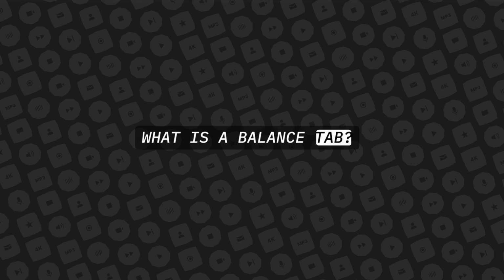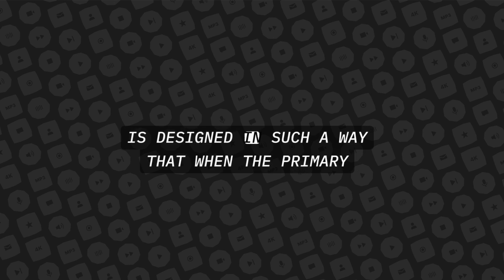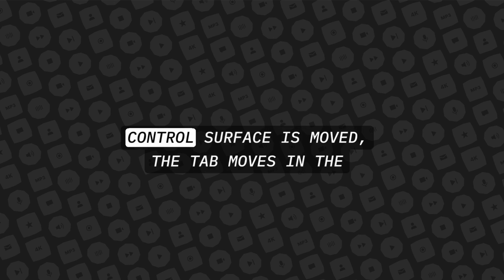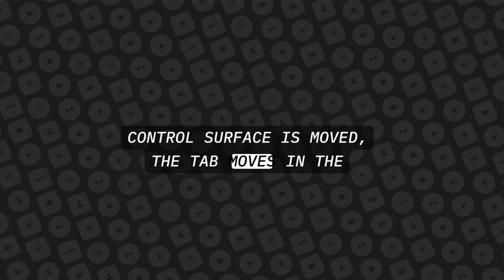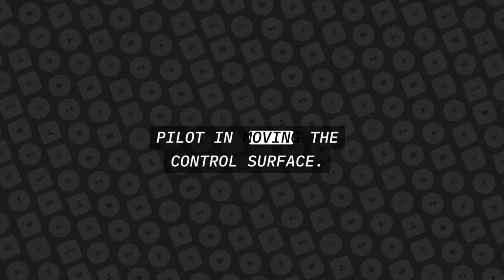What is a balance tab? It is an auxiliary control with fixed linkage that is designed in such a way that when the primary control surface is moved, the tab moves in the opposite direction. Aerodynamic forces acting on the tab assist the pilot in moving the control surface.